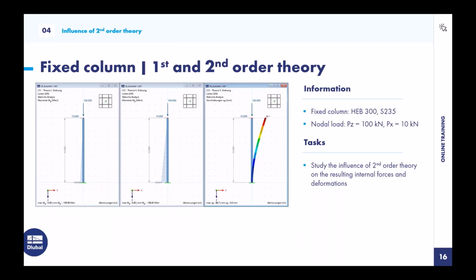This is especially the case when we have slender structures or elements. For example, in steel structures, we usually have quite slender columns, and if we want to calculate them under compression and also some lateral forces, we cannot neglect the influence of the deformations on the internal forces.